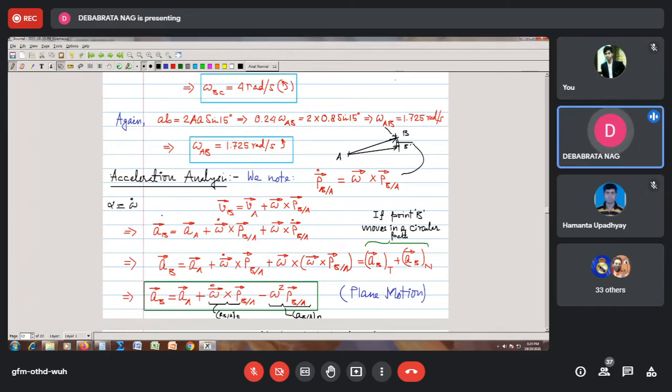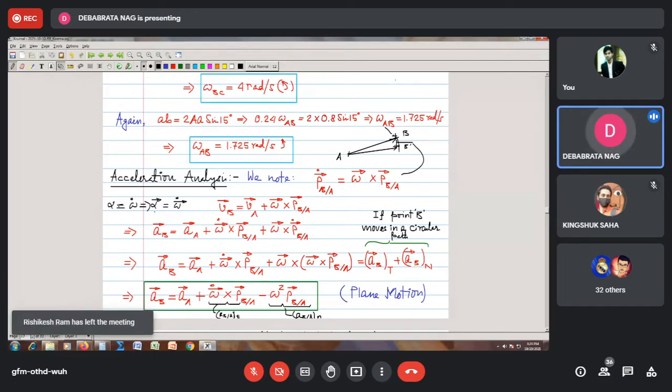However, for us it is simple. For us it is simple to note that angular acceleration is simply given by this. So I can say from here that alpha bar is equal to omega bar dot. And in plane motion, if we suppose the plane of motion to be the xy plane, then the angular velocity or the angular acceleration will be either along the positive k cap direction or along the negative k cap direction. All these things we have already told in our previous class.